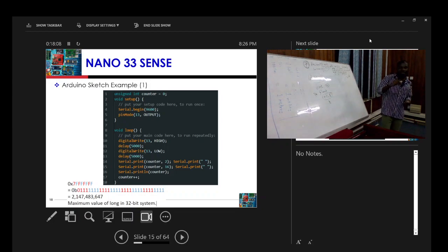So if I want the range, if I have a 4-bit number and I say that the number is signed, it means that the MSB is out of the number because that particular bit is used to identify the sign. The rest of it is the actual number. So if I have 1001 and I say it's signed, I have to forget about the MSB and use only these 3 bits to identify the number. 001 is 1. So this is negative 1.